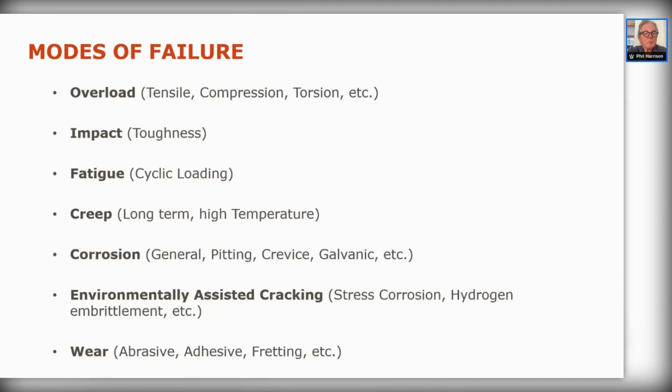As I said earlier, the major problem with this is if you have a tough material, it's great. But if you have something that isn't tough, which is brittle, it could fail at zero or have zero impact strength. This can happen in steels when they undergo ductile-brittle transition. Again, well known, and it can be designed out in most cases.